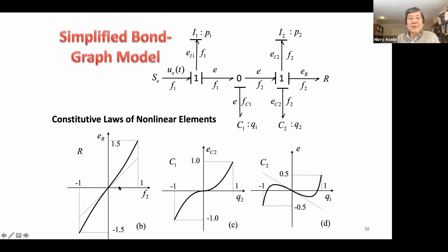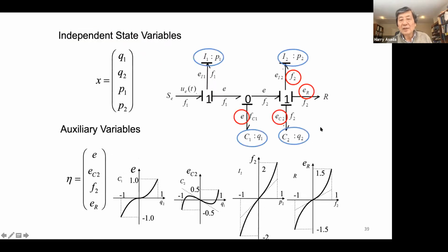So we built a simplified dynamic model of the excavation, the bucket interacting with the soil. We know the structure: here's a chunk of mass, here's a chunk of resistive elements involved, and how those elements are related. Based on that, we can draw the bond graph like this, right? The nonlinear functions involved in each element are a little bit of an academic exercise, but we make it a very drastic nonlinearity, such as this damping element and spring element going to the negative side of the slope. So very highly nonlinear.